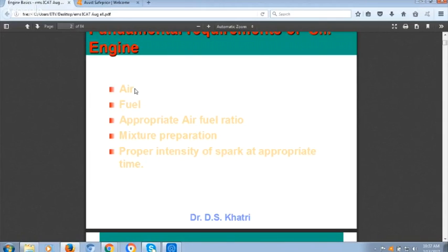So we have the air, then depending upon the type of fuel, we need a certain air fuel ratio. Suppose it is a petrol fuel. What is the air fuel ratio we need for combustion? How much? 17:1. Anybody else? 16:1. Anyone else? So we get two figures now, 16:1 and 17:1. Anything else? More precisely, it is around 14.7:1.